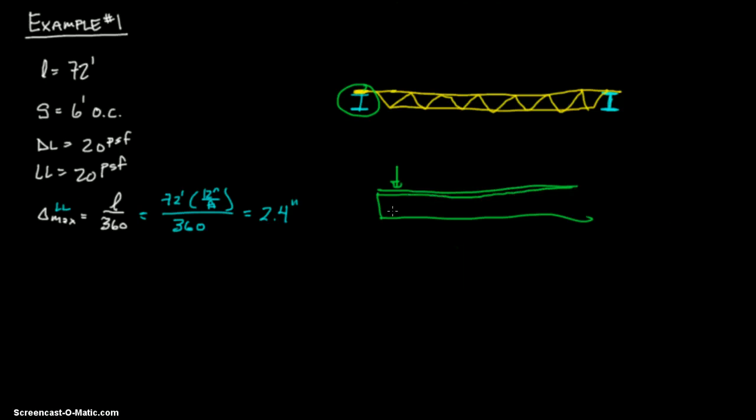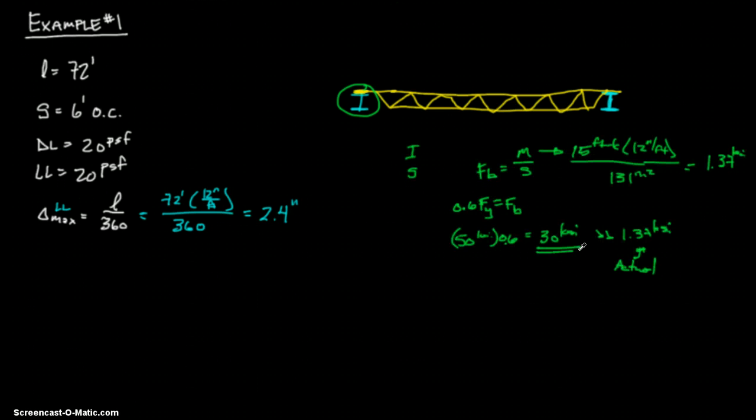It's kind of hard to make a little I-beam here. And then in this case we have 6 foot on center, so you'll have another point load, and a point load, all 6 foot on center, and then you'll have a column. So you'll have to figure that out. And that's pretty much your basic building system. Once again, it is more complicated than that, but that's the basic thought process. I was just trying to run you through that.